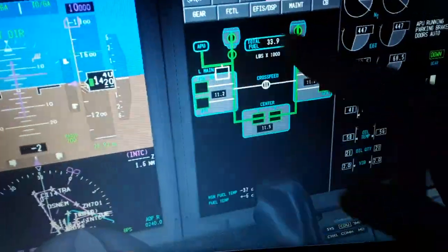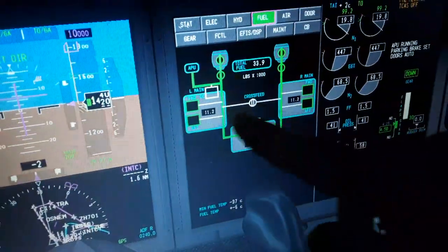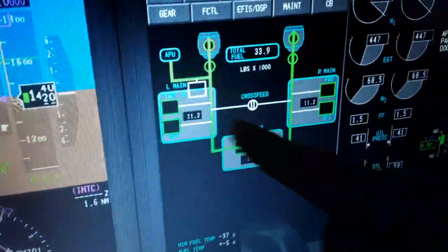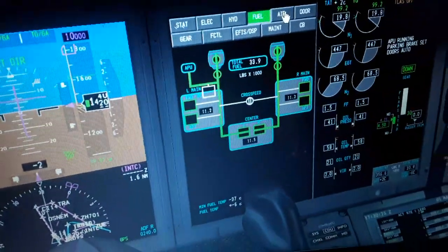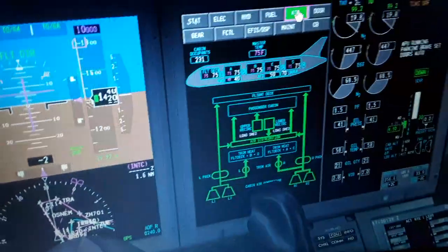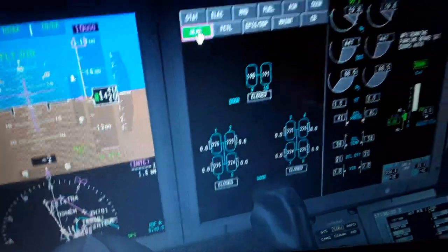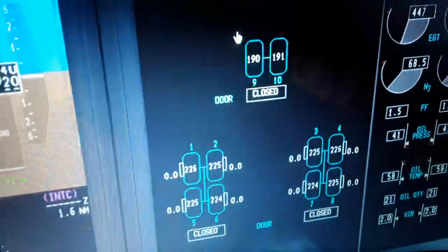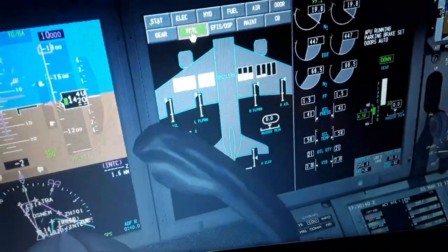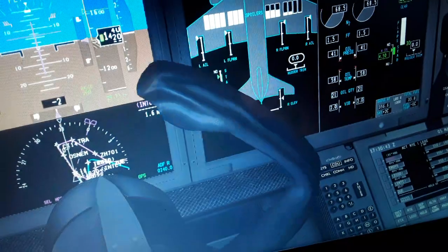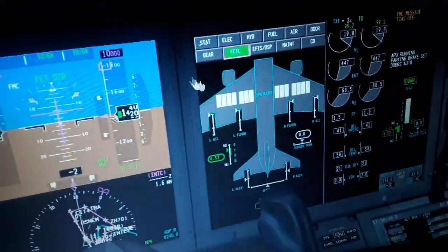The electronic control computers control the recirculation. We have the fuel transfer from the wing tanks and the center tank into the engines to heat it up in flight. Also the lubricant and the oil. We have the air pressurization for hydraulic fluid tanks, oxygen pressurization. The doors are closed, the cabin can be pressurized, landing gear and the nozzle, pressure of tires and flight controls. You can see here the temperature of the tires. You can see also aileron, spoilers, the flight controls movement, the rudder pedals, the tail, and the horizontal trim stabilizer.